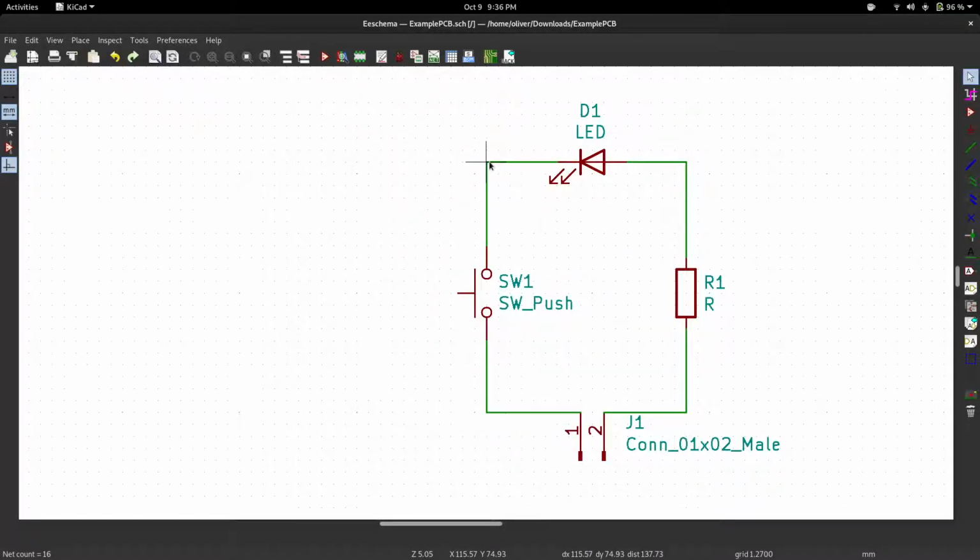Design rule check is something you run on the layout of the PCB, and it checks things like, is the clearance around this thing large enough that it won't accidentally short out? Is there enough thermal clearance? Actually, that's a complicated topic, but you can verify that certain aspects of your design will not have issues, and this can be done automatically.